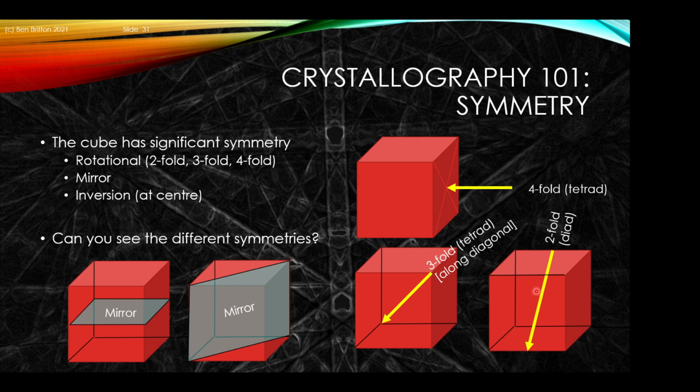The 2-fold, that dyad axis, is pointing from the center of the front here towards the center of the back here. That's that dyad axis. We can see that there are 2 importantly different mirror planes. We have this mirror plane that cuts halfway in the cube, perpendicular to one of the A-type directions. We have this other mirror plane that is running along what we will call in a minute the 1, 1, 0 type plane, we'll see in a bit, that's cutting along the diagonal here. And if we do a reflection in that crystal, we'll see that this atom reflects to this site over here.